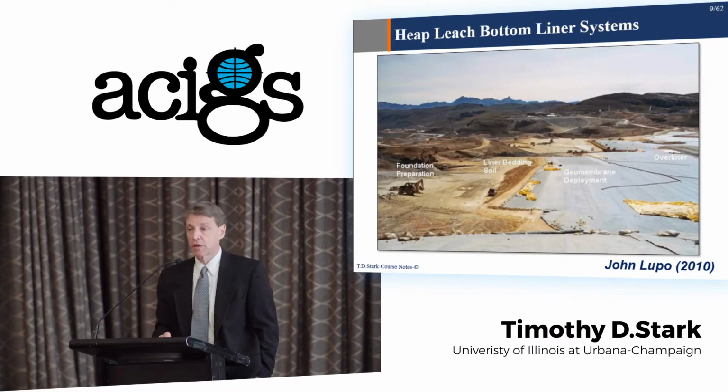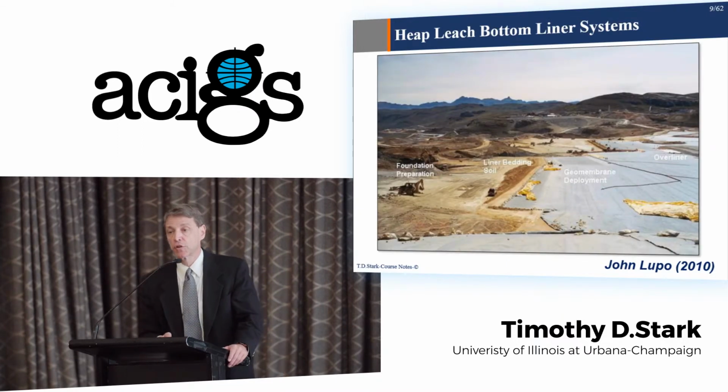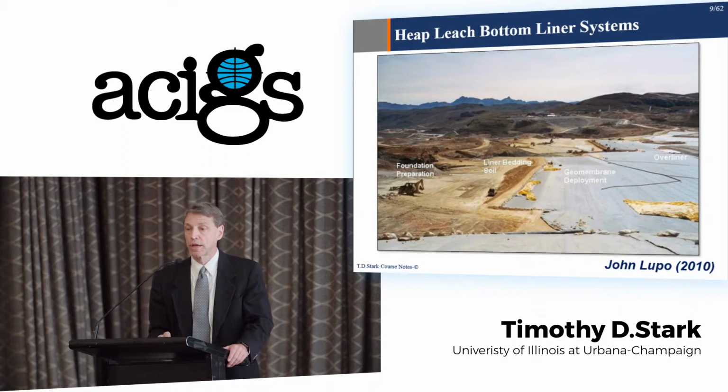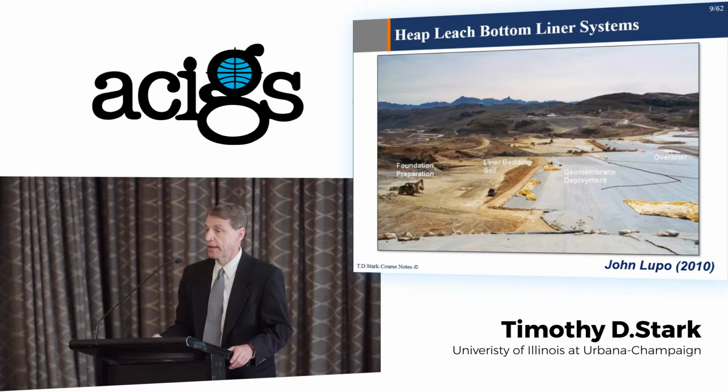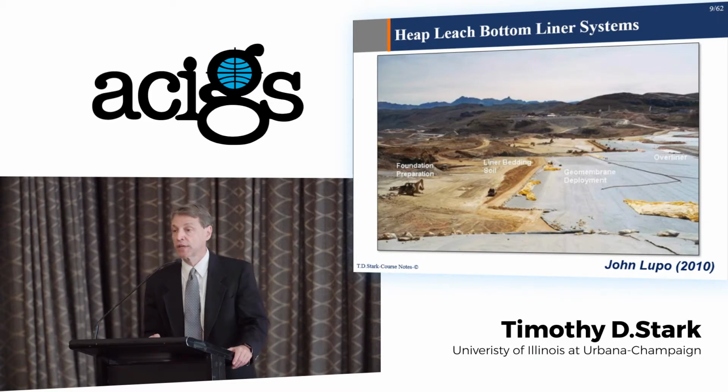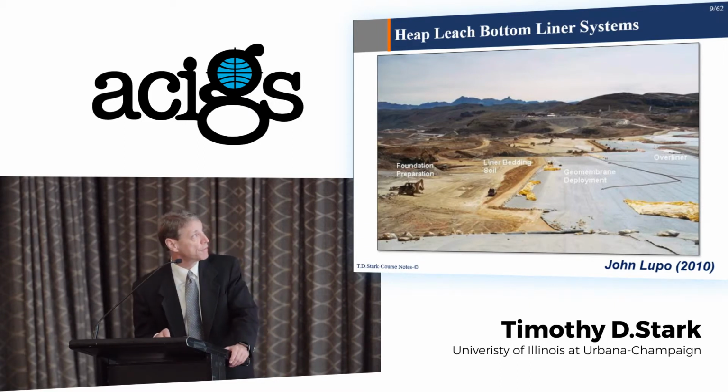Okay, so what does it look like in practice? Here is construction of a single liner system. Here's the foundation preparation on the left, the liner bedding soil coming in next, and the geomembrane deployment coming over top of that. So it's a pretty sequenced operation, very, very efficient.